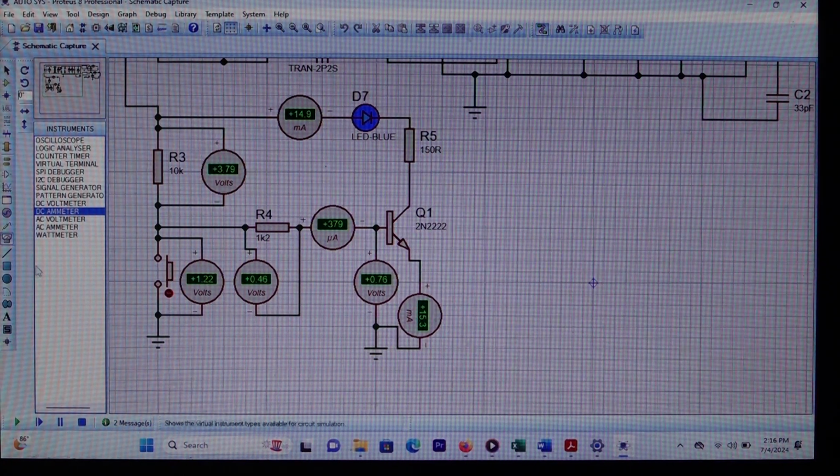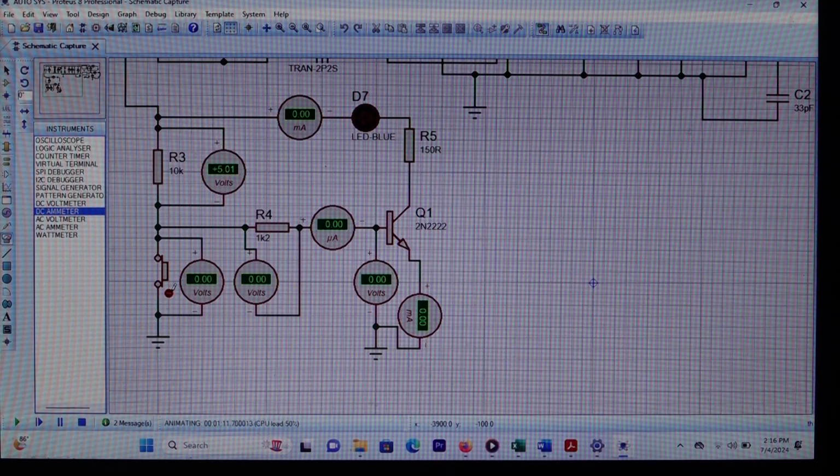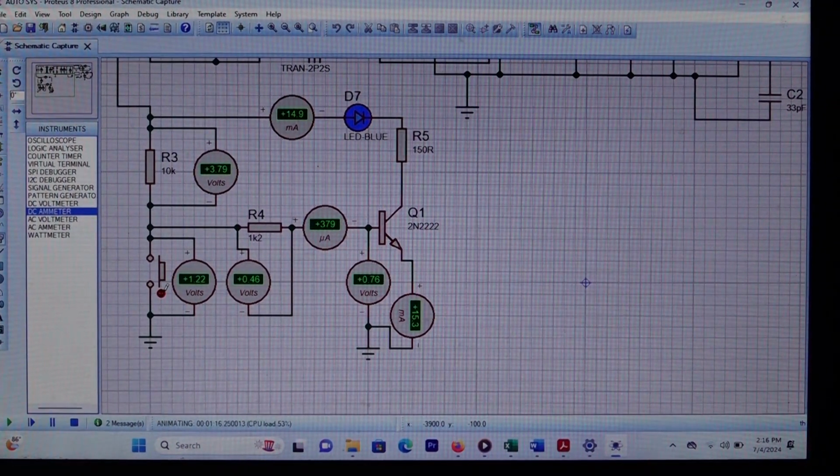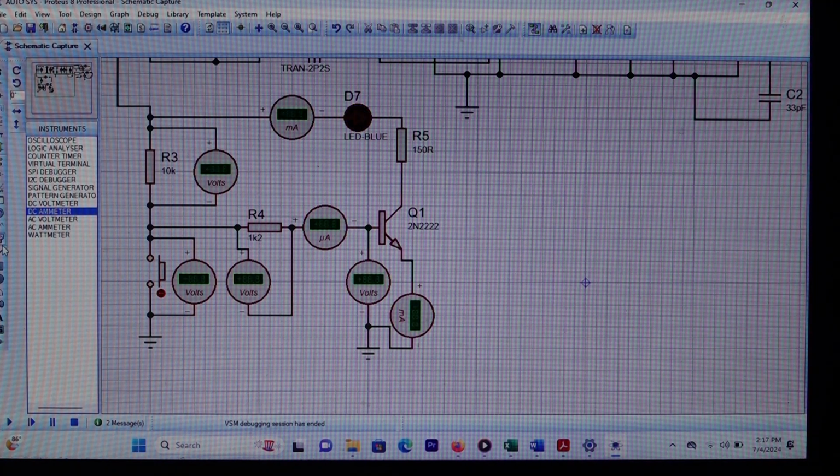Okay, so if you press the push button, the transistor turns off, or operates in the cut-off region. If you release it, then the transistor operates in the saturation region. So that is a good step. We have tested our digital sensor input unit, and it works. And you have also tested our NPN bipolar junction transistor switch, and it works. But we still have another testing point, if you do remember.